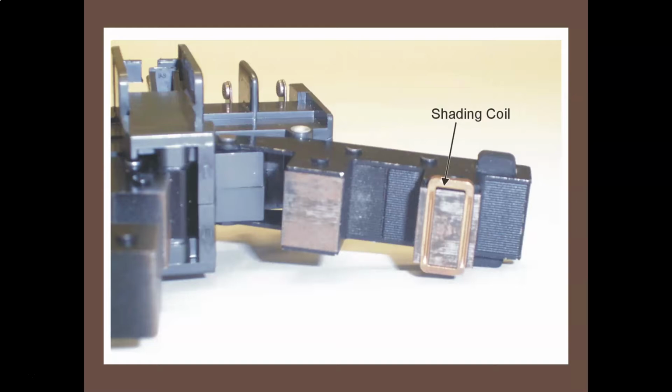So my armature is going to want to pull away, and if my armature pulls away, I'm going to get arcing. This is happening 60 times a second, so it's very quick. But my armature is going to pull away, and then it's going to jump back up to the seal-in voltage, and your armature is going to slam shut again. So what you can have happening is you get chatter. Your armature is opening and closing super quickly, so you can hear a buzzing or a chattering noise coming from your contactor, which is not good. You don't want that. It's creating heat. It can damage the actual armature and the contacts because it's all vibrating and moving very quickly.